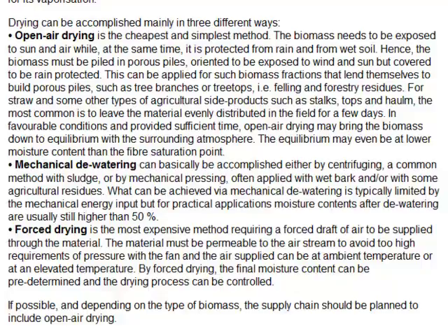The most expensive method by far is forced drying. Forced drying is to add heat and add ventilation air to the biomass, to heat up and vaporize the water, and then to carry the water vapor away from the material. Forced drying can only be applied in case there is economy enough to carry it.